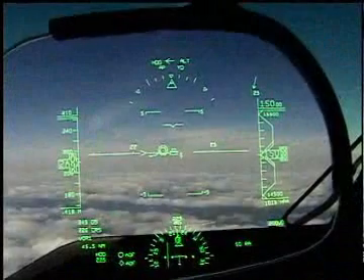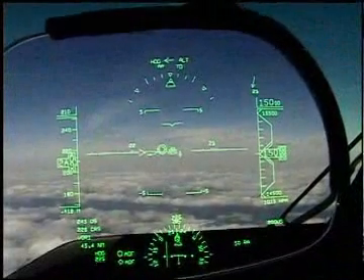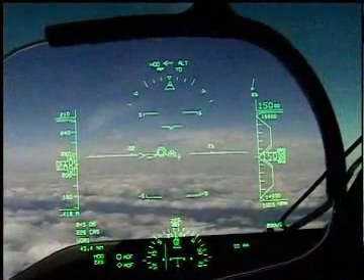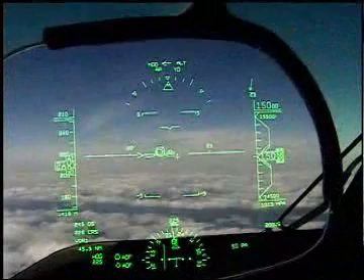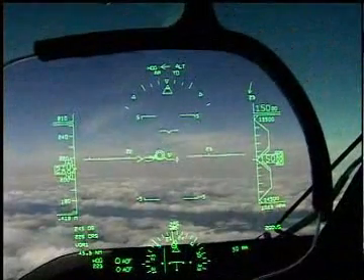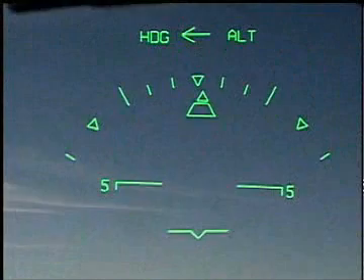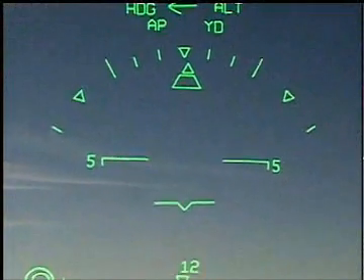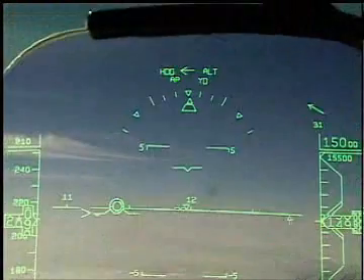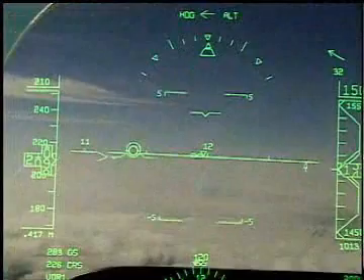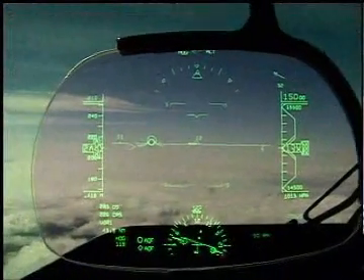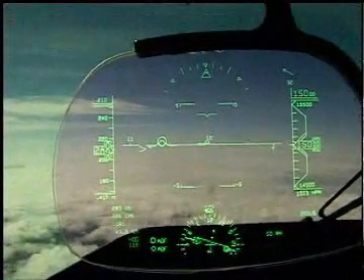During ILS/VOR operations, course deviation is displayed as a course deviation indicator line within the HSI compass. The FGS Flight Director Armed and Captured modes, autopilot status, yaw damper status, and the flight director coupled arrows are indicated across the top of the display, similar to the head-down primary flight display.